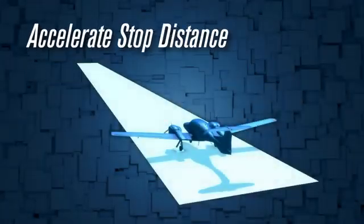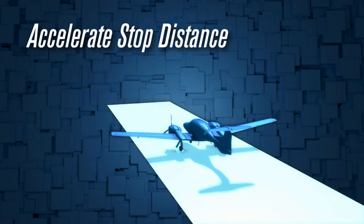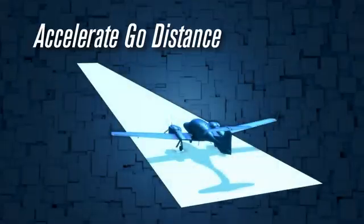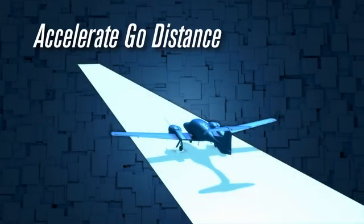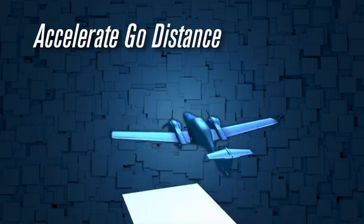Accelerate stop distance: the total ground distance it takes for a multi-engine to accelerate to rotation speed, experience an engine failure, and come to a stop. Accelerate go distance: the horizontal distance required to continue the takeoff and climb to 50 feet above ground level, assuming an engine failure occurs at rotation as specified by the manufacturer.